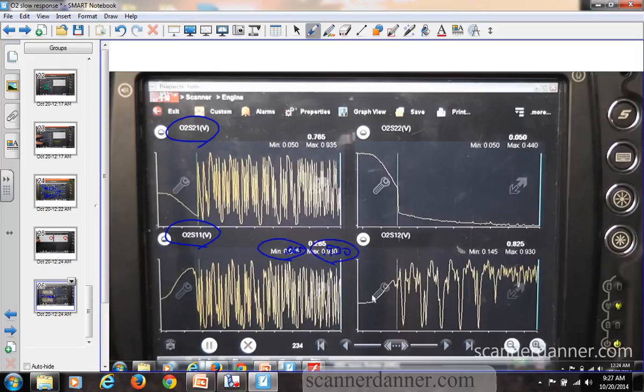How's my amplitude on that one? I think you can see that number. 0.05, 0.93. How's my amplitude? That's good. That's 50 millivolts, and that's 935 millivolts. I'm okay with that. Remember, I'm okay with below 200 and above 800, just not inside that window.